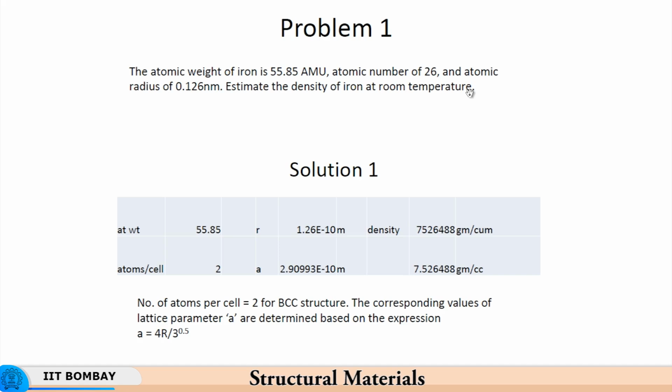Normally what we do is we calculate the density based on experiments, or we take an experimentally determined value depending on the alloy content of steel. For instance, we take the percentage of different alloying elements, multiply each by its density, and get a linear estimate of the density of that steel or alloy steel based on the alloying elements which have been added.